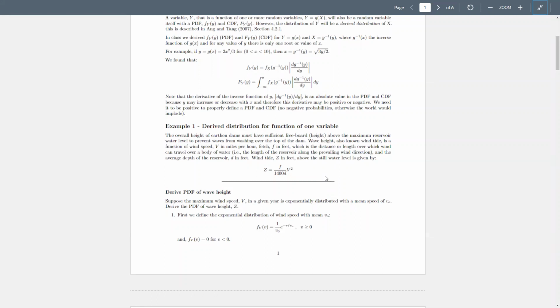Yeah, and so for example, this particular equation is used to evaluate wave heights for reservoirs. If you're building a dam on a reservoir, how much freeboard do you need above the high water elevation so that waves don't wash over it or cause erosion? Maybe you're going to put some riprap on the side of the dam, so this would be a design equation for that. In which case, maybe you've got a windrose or an anemometer, and you've got some information about wind in the direction of the fetch of the dam, so it has this distribution, right? So maximum wind speed.